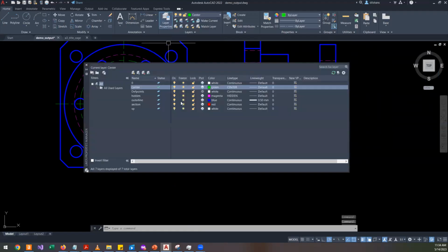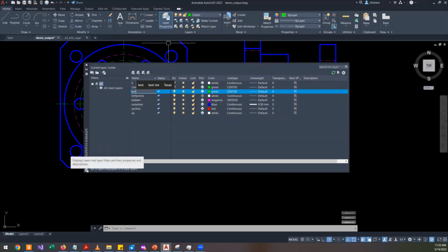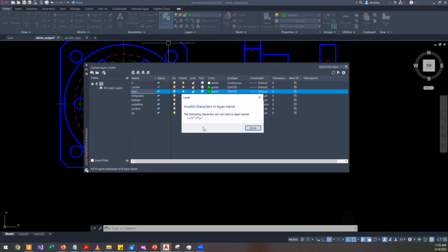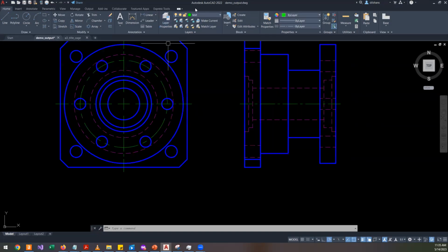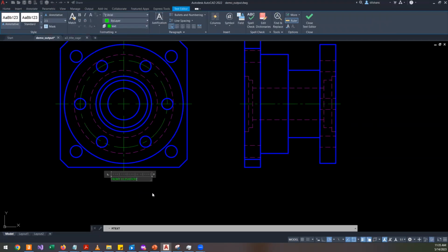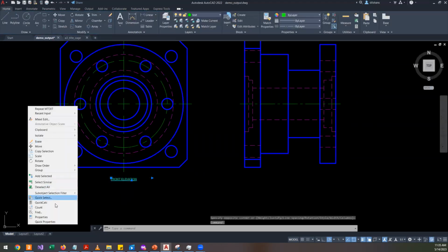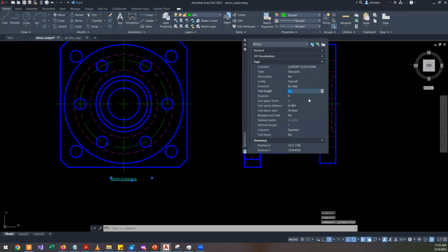If it is 5 millimeters, so here you need to include the text. Okay, let me make a layer. Text, with elevation. Control A, Control U. I can go to properties and update the value.